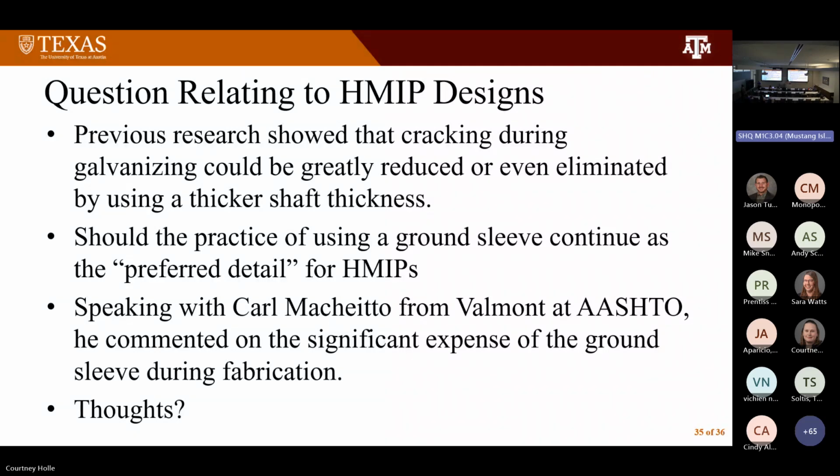But if you go out and you say, this crack was 2.5 inches long, now it's 3 inches long, or here's the depth, then that's one of the things where you may want to consider repairing this. Like one of the things we had found, Mike Engelhart led the last project that we had done on this, and they're finding that as far as repair, if you've got through thickness, they need to be replaced. You really can't repair that. You don't want to get to that stage. If it's through thickness, you usually can visually see it probably.